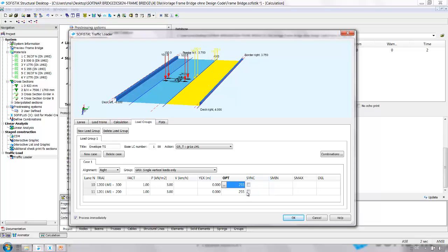Then we have another 2 columns, and the program will automatically place the loading at the most unfavorable position inside the above region. To achieve this, all selected points of the load train are placed at the 4 extremes of the influence lines, and the maximum value of this initial position is used for the detailed iteration. However, the region can be input for special cases. If you need more details for these columns, please look at the LR menu.